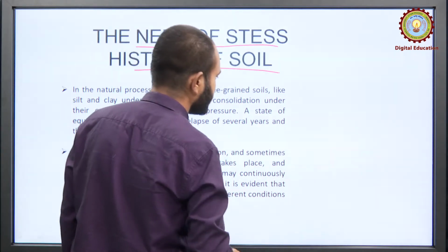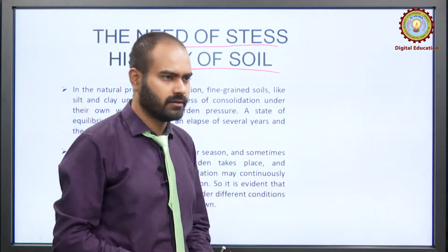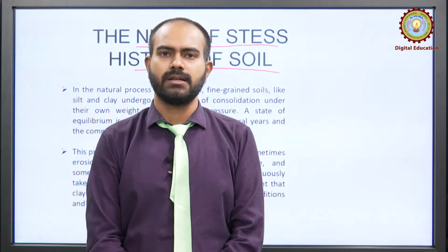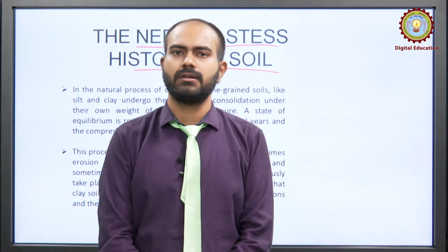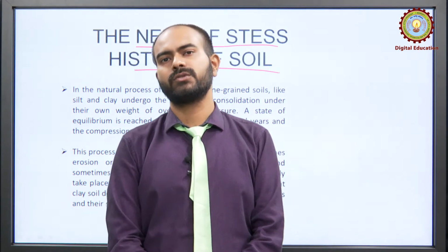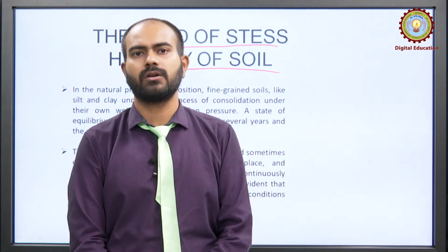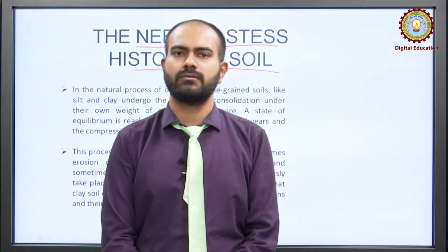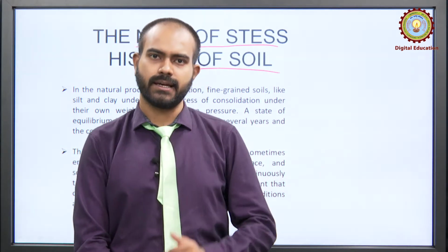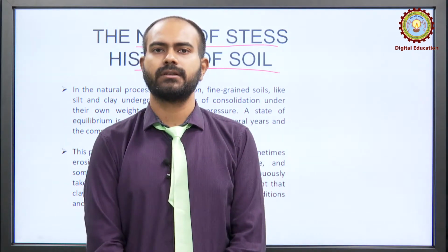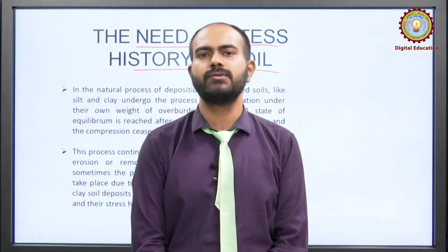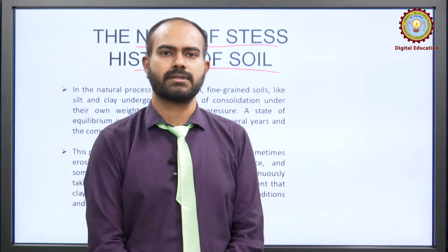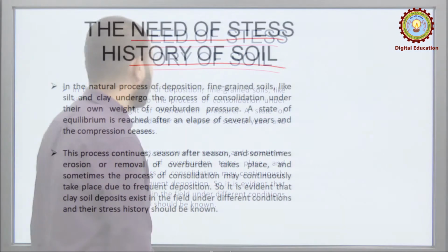Stress history means that perhaps at a time in the history of the soil, the soil might have got an overburden which was greater than the overburden or the stress which it is carrying now. So, we will be seeing these things and also what the use of this stress history is for engineering purposes. Okay. So, let us see.